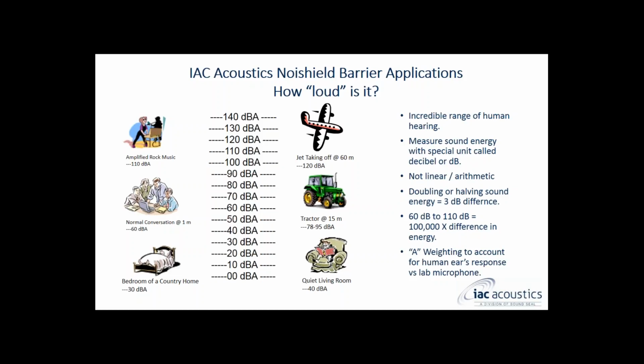So if we took a measurement of some acoustic experience with a perfect microphone, the total that the perfect microphone is measuring may be more or less than what we might experience as a human. We use the dBA designation to indicate that that weighting has already been applied to the measurement so that the numbers are reflective of what a person would experience.